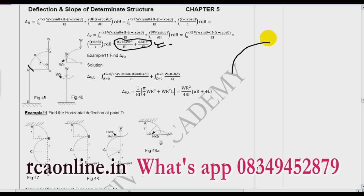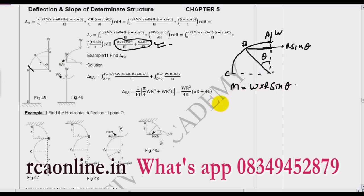For the AC part, this is my W and this is 1/4 of a circle. So I will take any point in between and the angle is theta. So what is my lever arm? My lever arm is R sin theta. So what is my bending moment equation? It will be W into R sin theta. So what is del M by del W? It will be R sin theta.